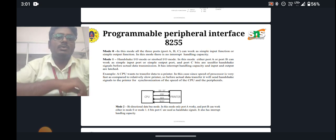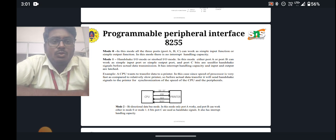For example, a CPU wants to transfer data to a printer. Since the speed of the processor is very fast compared to the relatively slow printer, before the actual data transfer, handshake signals are sent to the printer for synchronization of the speed of the CPU and the peripheral.